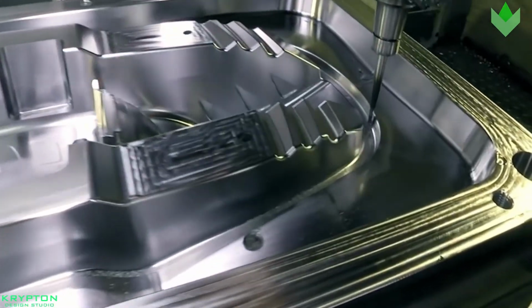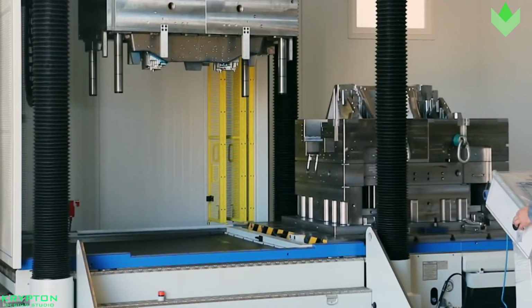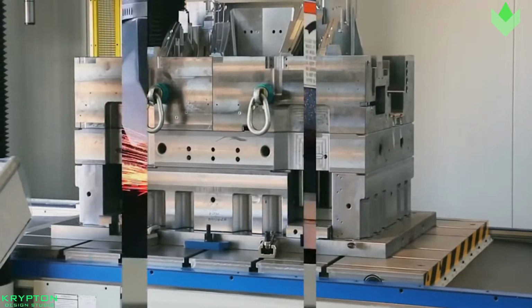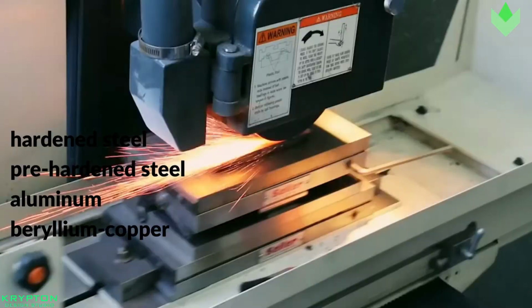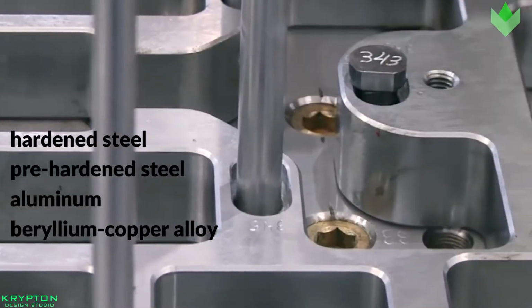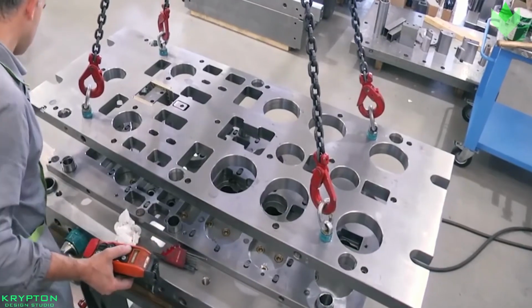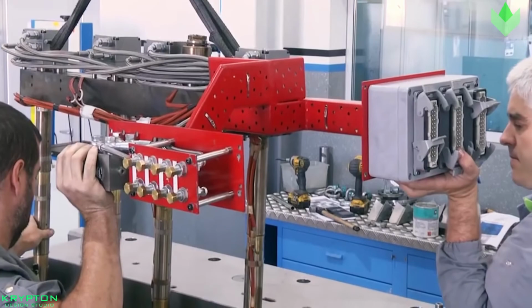Mold. The mold or die refers to the tooling used to produce plastic parts in molding. Traditionally, injection molds have been expensive to manufacture and were only used in high-volume production applications where thousands of parts were produced. Molds are typically constructed from hardened steel, pre-hardened steel, aluminum, and beryllium copper alloy. Steel molds generally cost more to construct but offer a longer lifespan that will offset the higher initial cost over the higher number of parts made before wearing out.